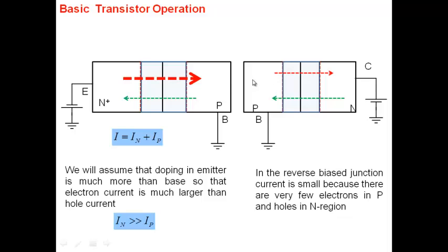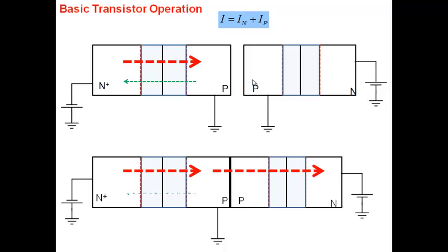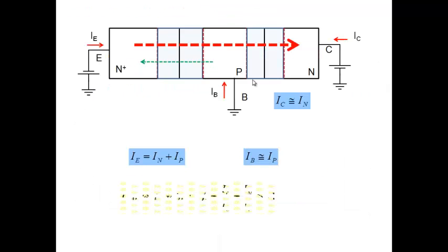And therefore nothing changes. That's why, when you go back to your bipolar transistor, you can see here that as I change my collector bias, it does not change the supply of these electrons at all. The supply of these electrons is under the control of this junction. This junction is controlling the supply of electrons. This junction doesn't do anything to the supply of electrons. So you can make it 1 volt or 2 volt or 3 volt, and nothing happens to this red arrow that you see here. The number of electrons that flow still remains the same.